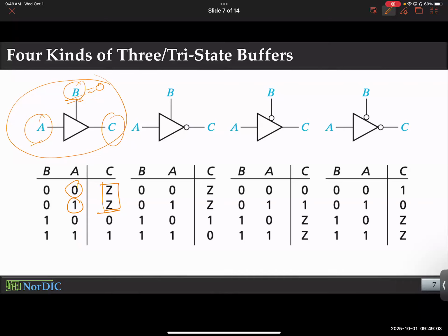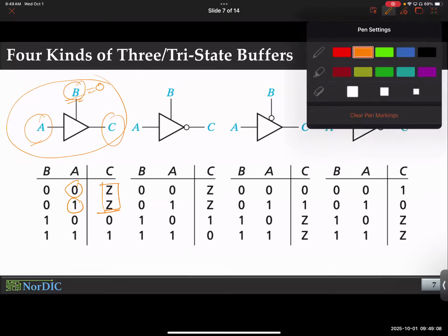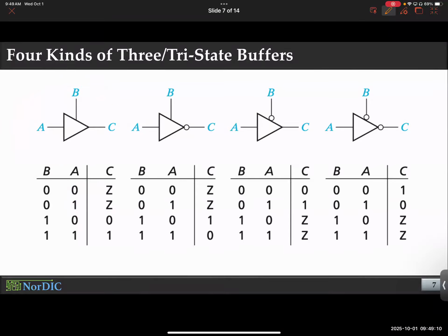If I were you, I would have asked this. I had this exact same question when I was in your stage. Okay, how is that different from not having anything? If it is 0, then what's the big deal? Basically, what it does is when your input is not driving an output, say imagine your output was VDD in the previous cycle. It can randomly change by environmental aberration. Because of noise, it could go slightly up to VDD plus delta V, or it could go down minus delta V. It could go up or down slightly.